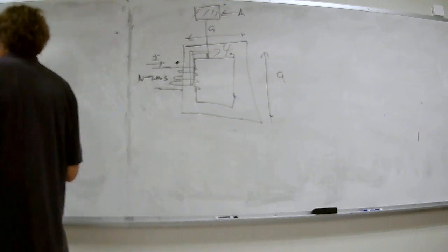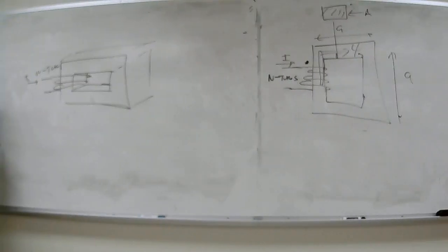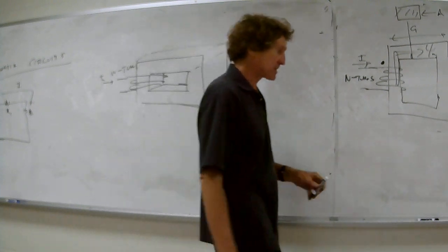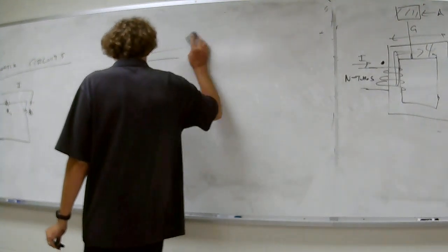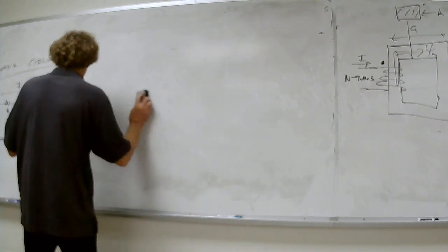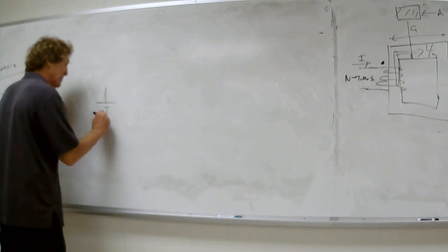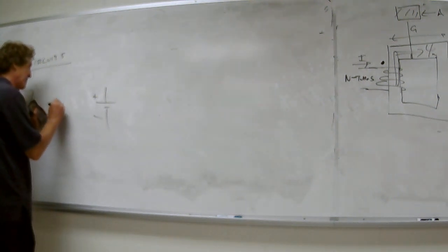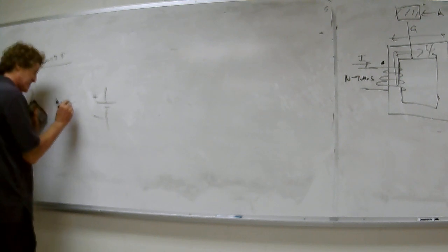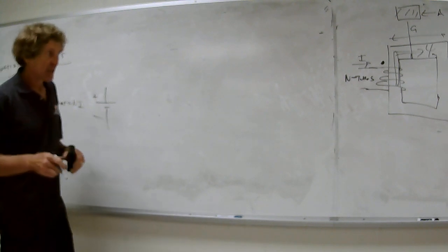So, like over here, you had a voltage, right? Now for a magnetic circuit, I'm going to draw it right here, parallels this. Matter of fact, let me get rid of that drawing so I can do it this way. Let me finish this train of thought. Instead of a voltage, we're going to have something that's akin to a voltage. It's a magnetomotive force, and MMF is simply given as the number of turns times I.